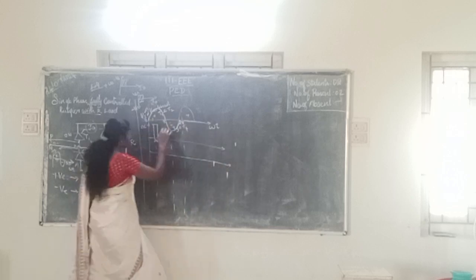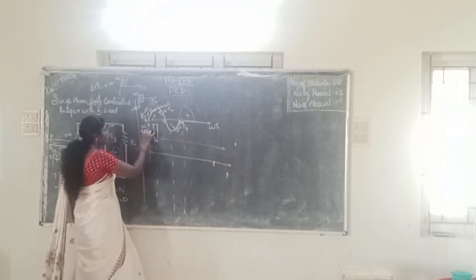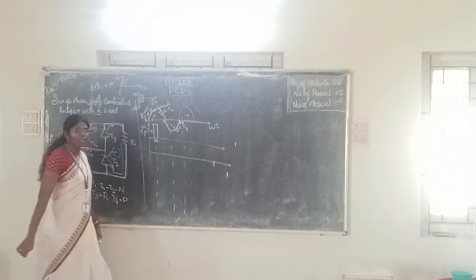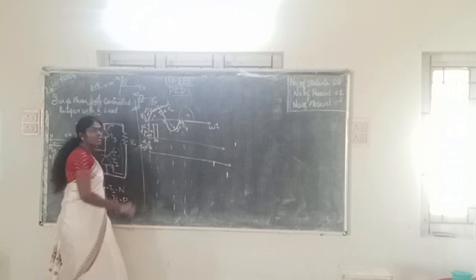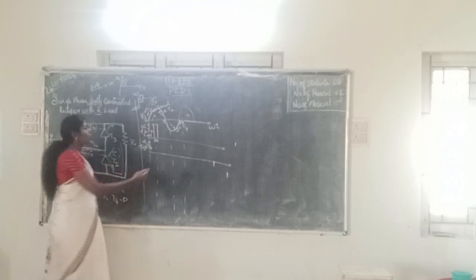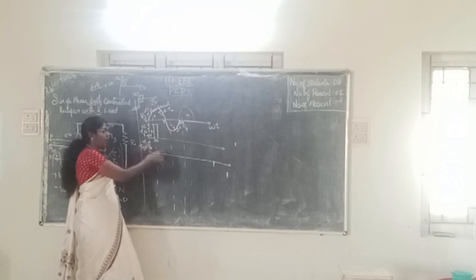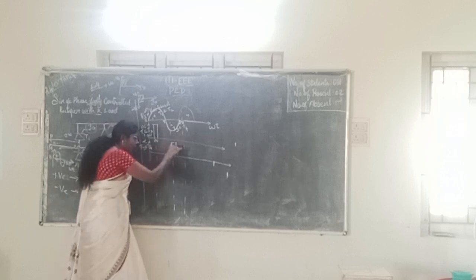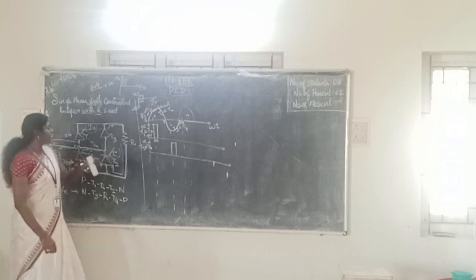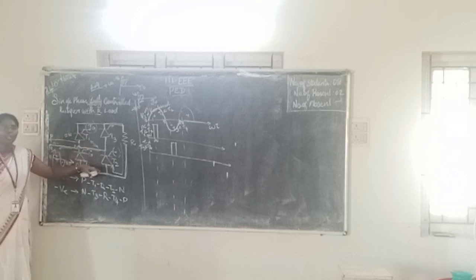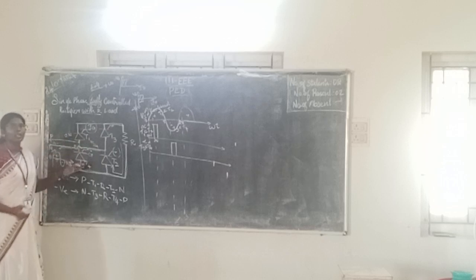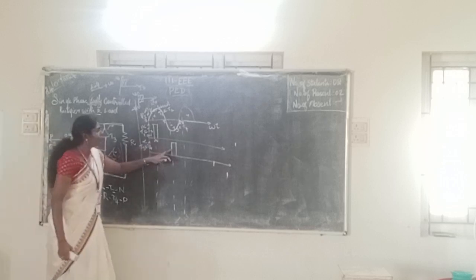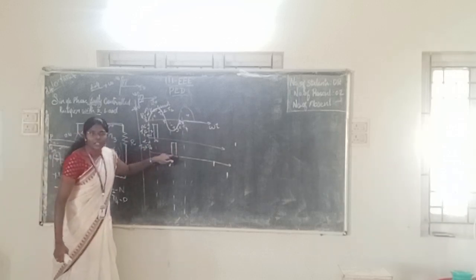During the positive half cycle, at this condition T1 and T2 are in the on mode. And whenever T3 and T4 are in the on state, this will be the negative half cycle. So the firing angle will be given to the gate terminals of T3 as well as T4, during the alpha condition in the negative half cycle.